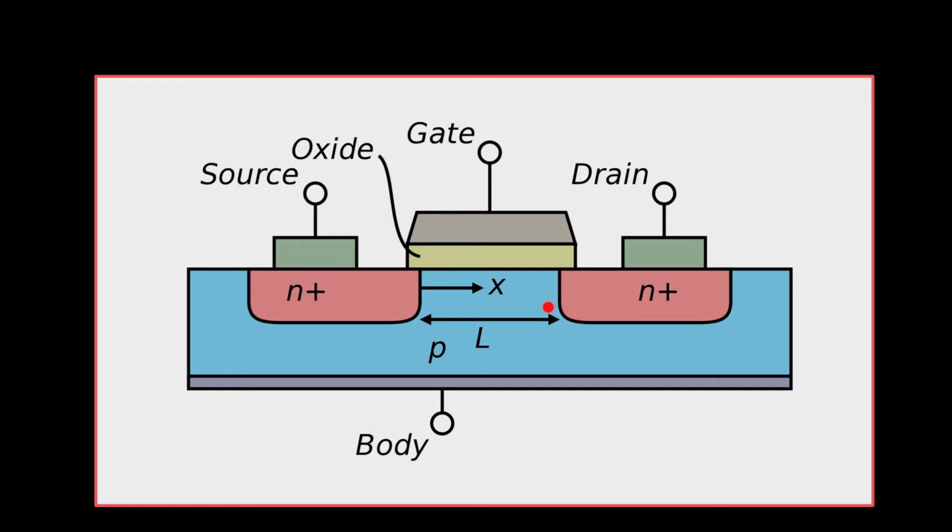You're going to get pinch off, and then you might ask, well, how does our inverter work? Because initially the drain is going to be close to the positive supply rail. So if the drain is close to the positive supply rail, the gate increases in voltage to open up the channel. Yes, because the drain is much higher than the body, which is normally connected to the source, there will be a pinch-off effect here, but you'll get a little bit of current flowing. And as you get a little bit of current flowing, then in the inverter circuit, that's going to decrease the voltage at the drain.